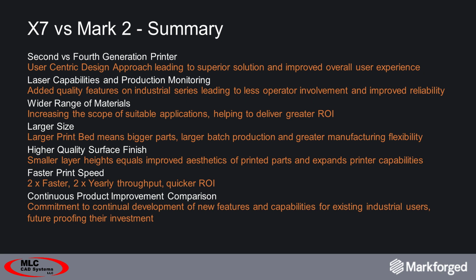The laser micrometer on board on the print head serves a variety of functions that we discussed today, including adaptive level bed scan. Before every print, that laser is used to measure the bed flatness, which is then accounted for in the first 5 layers of the print to ensure that perfect part. That laser also helps the printer perform that pre-print calibration as well as the in-process inspection we reviewed.